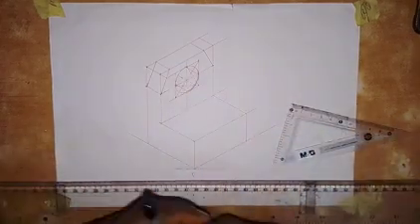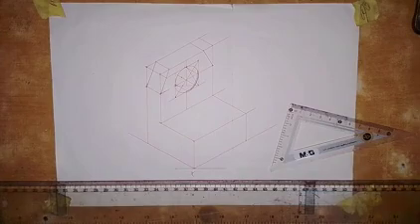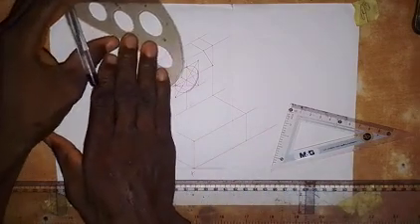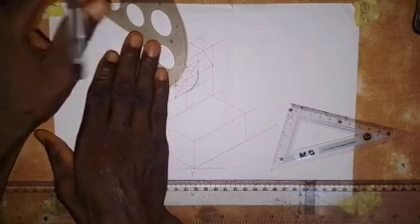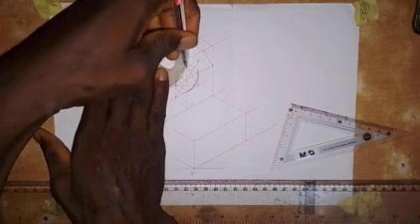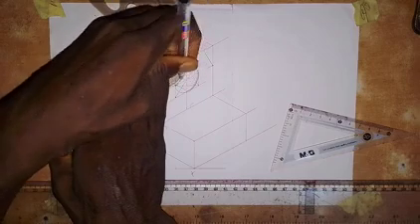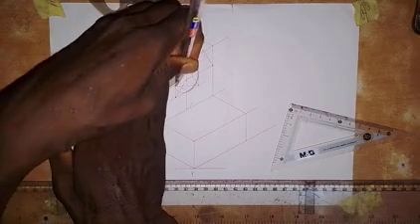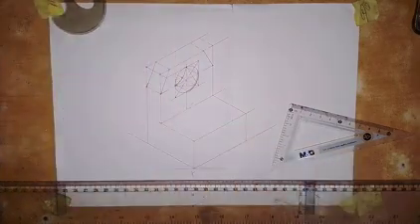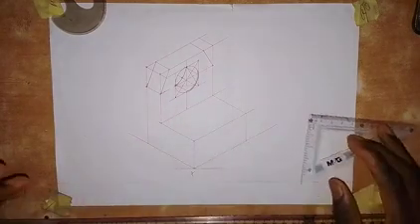So we are going to use the French curve to produce that curve. It goes like this. Just set your French curve along the points. Set it very well, and then we just draw. So the curve is like this. That's the other part of the hole at the back. So this is how it will show. All right, so I believe this is clear to you.